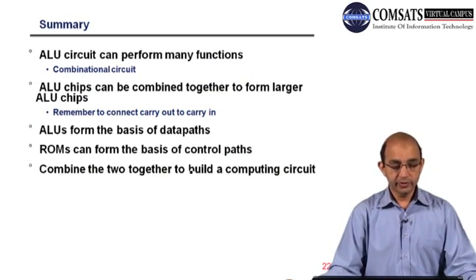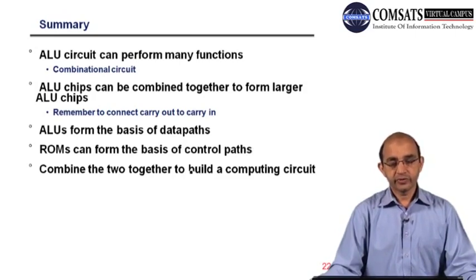for ALU. And today we have discussed PLAs, and we mentioned that by having PLAs we can have simplification. If we talk about ROMs, we need to use a decoder in order to have addressing. But the problem with the decoder is that it generates all the possible minterms, even if we are not using all those minterms.